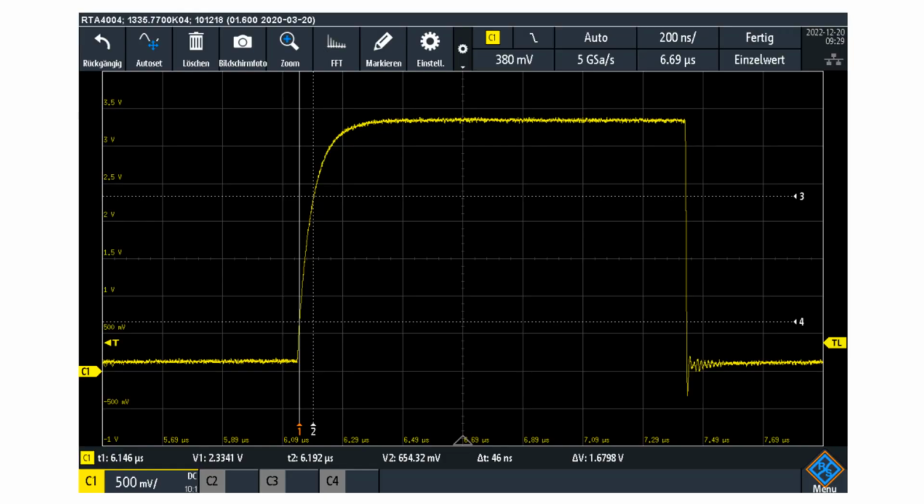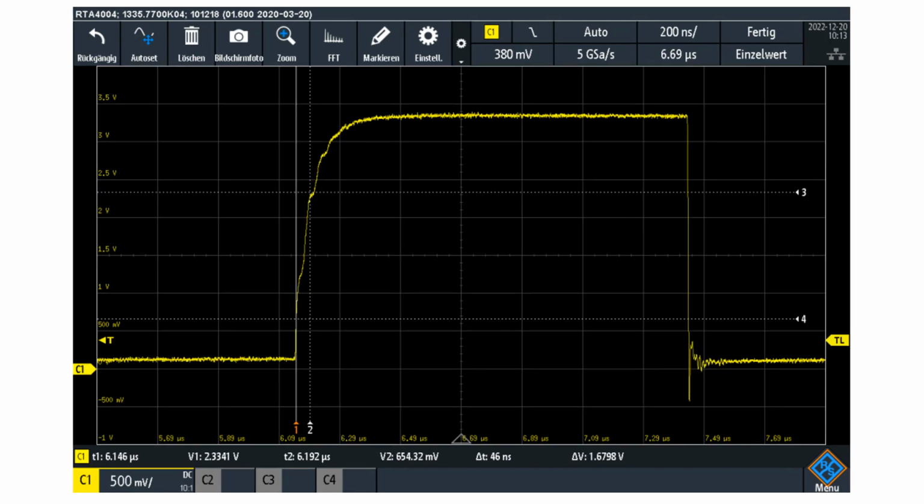During these measurements, the voltage curve on the SCL line was always measured. First, we have the reference measurement with 1 kiloohm pull-ups without further changes to the Featherwing hardware, which equals 46 nanoseconds rise time. Our next measurement is with 1 kiloohm pull-ups plus a multi-layer surface mount ferrite plus a TVS diode array, and also includes a 20 centimeter cable, giving us 46 nanoseconds rise time.